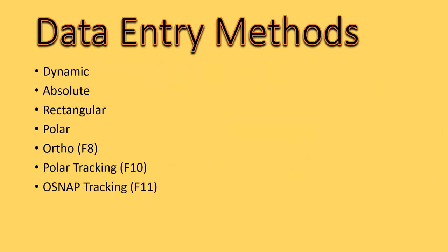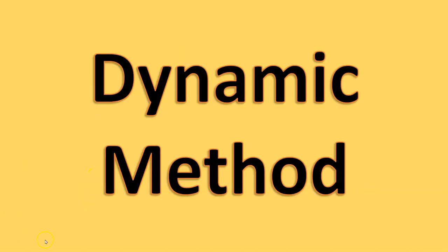Now here are the standard methods, or different ways of adding things or putting data into AutoCAD. So we're going to start with the dynamic. Anytime you hear that term in AutoCAD, that just means that it's going to give you total control of how you want to do it. And one command that really demonstrates that is going to be the lengthen command.